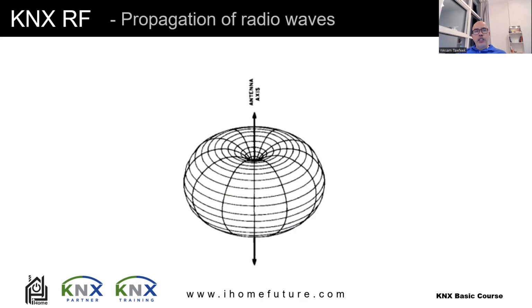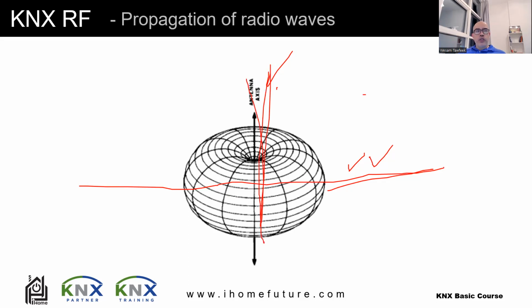He wants here to tell you that the signal of the waves from the device is not the same in all directions. Okay, so here it's mostly more strength, here less strength, and here is more strength. So we know from KNX and from Z-Wave courses that the horizontal part is mostly stronger than the vertical part. From Z-Wave, we know that it's almost 30%. So the vertical on the antenna is 30% less than the horizontal part.